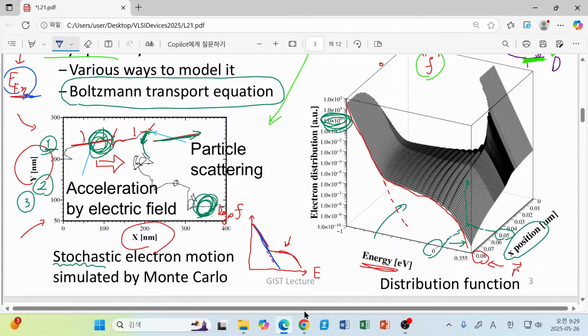With this quasi-Fermi level, we can define this majority part, and the remaining part is not our concern, or it is a concern. It just tries to find the majority electrons, the main body of the electron gas. This is quite well described by the electron quasi-Fermi potential, energy or potential.